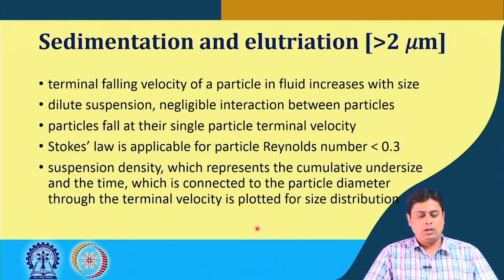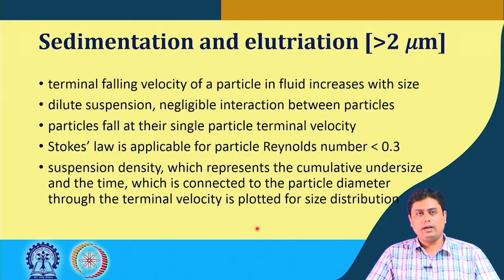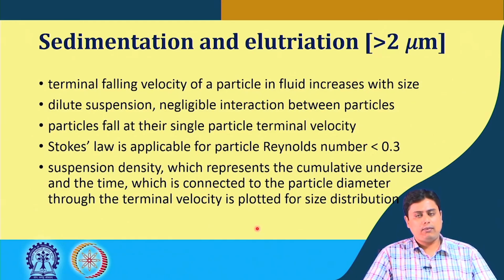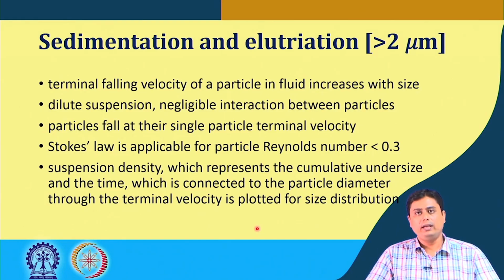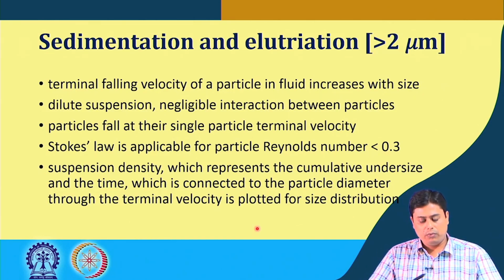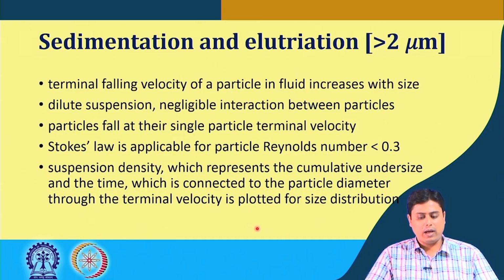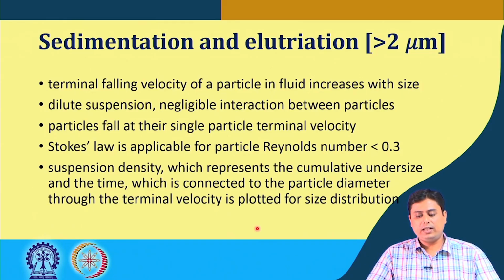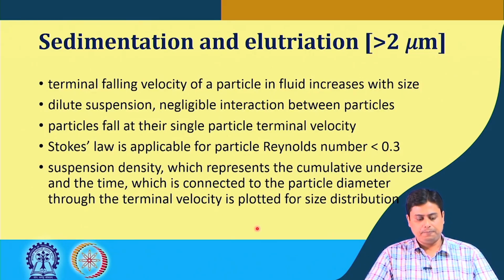Here, the principle of this sedimentation process is based on the fact that the terminal falling velocity of a particle in a fluid increases with size. If you remember Stokes' law, which, as I mentioned, is prerequisite fluid mechanics knowledge that you need to have for this course, you would understand that this terminal falling velocity is essentially dependent on the particle size.